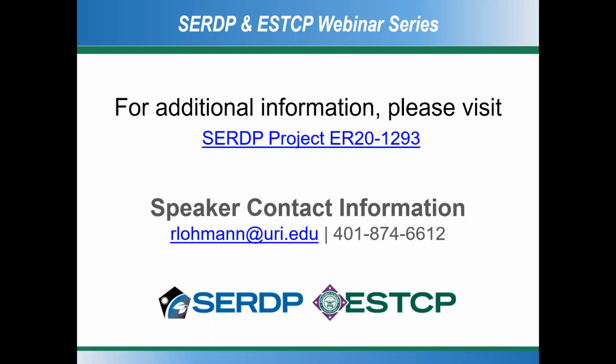This next question is from the North Carolina Department of Environmental Quality. Do the passive samplers address colloidal transport? And if not, is that a limitation to the method? It's a good question. I guess it depends on your perspective. So no, any of the tools that we develop, and I assume almost everybody else that works on passive samplers, do not work with colloids.